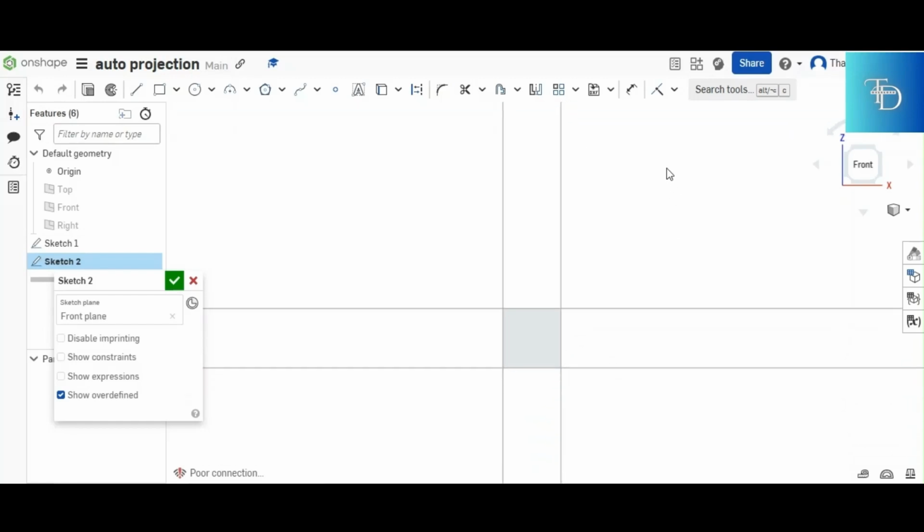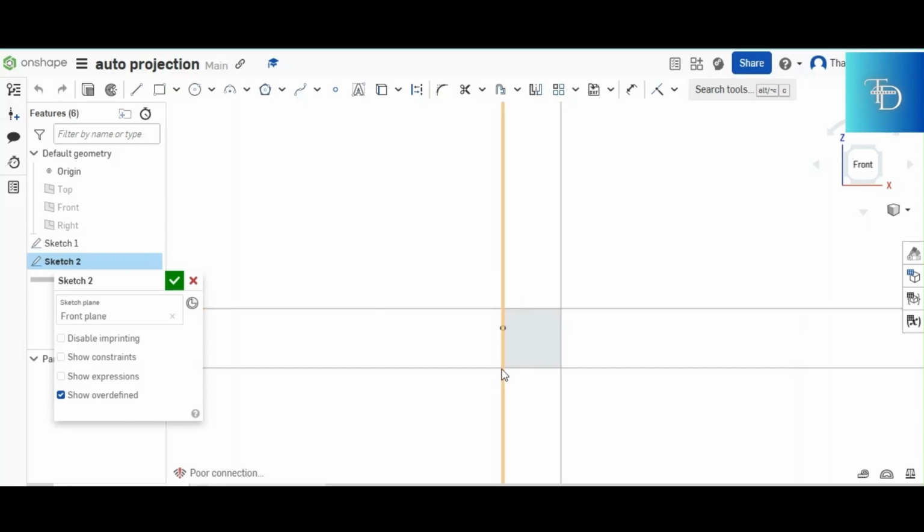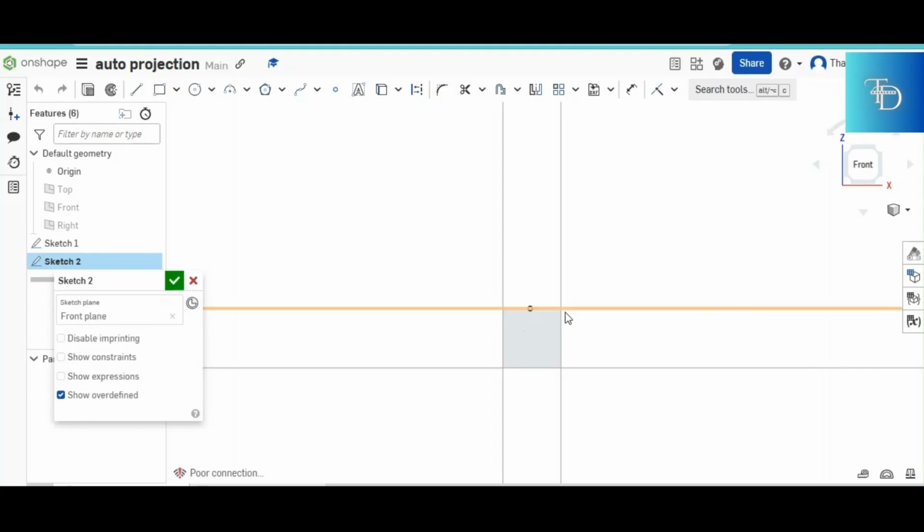The top right corner of your top view is going to start where? There. As this shows you, here we have the bottom right corner, there we have the bottom left corner, there we have the top right corner. Because there is a front, you take the bottom right corner of the front view, you put it there. You take the bottom left corner of your left view, you put it here at this bottom left, right there.